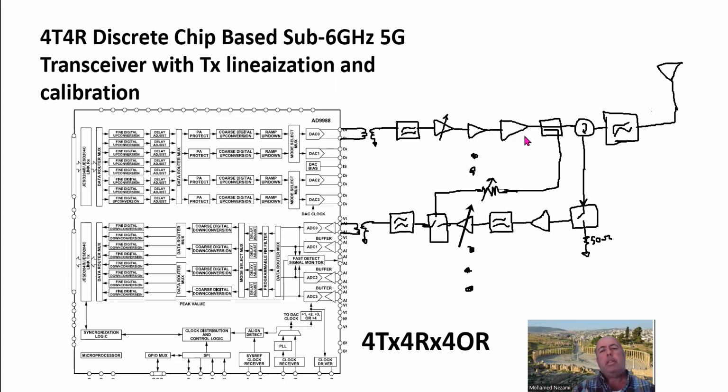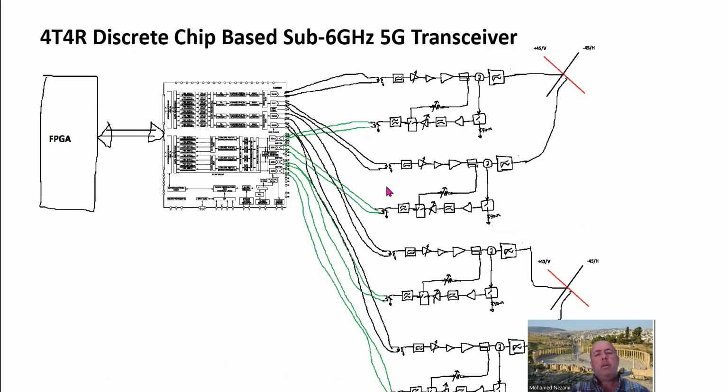If you don't change the dynamics of the signal, the same signal level, same drive level, same temperature, same modulation, then you basically periodically go in and figure out linearization in here. You linearize this PA and you can set the power level, equalize the output or whatever you need to do for this PA, utilizing methods of loopback, okay?